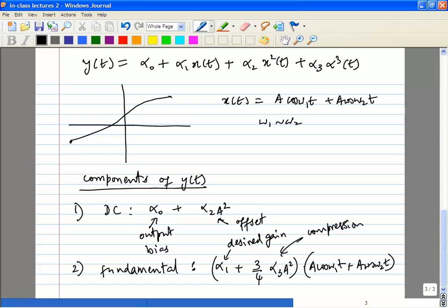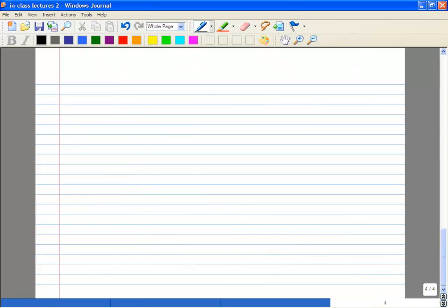I think we showed this last week, so your input-output, output power versus input power, will look like this. It just compresses normally like this, and so you might get something like this. It will still compress, but maybe at a higher power. So should we take the expanding 1 dB point? No, it will still be the compressive 1 dB point. You will still take the compressive 1 dB point.